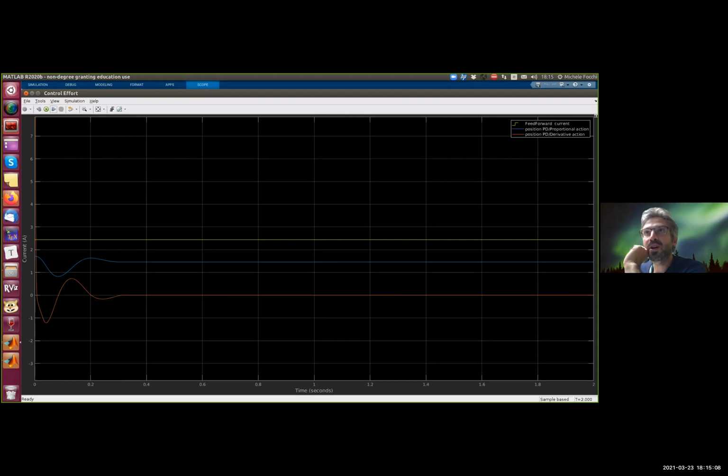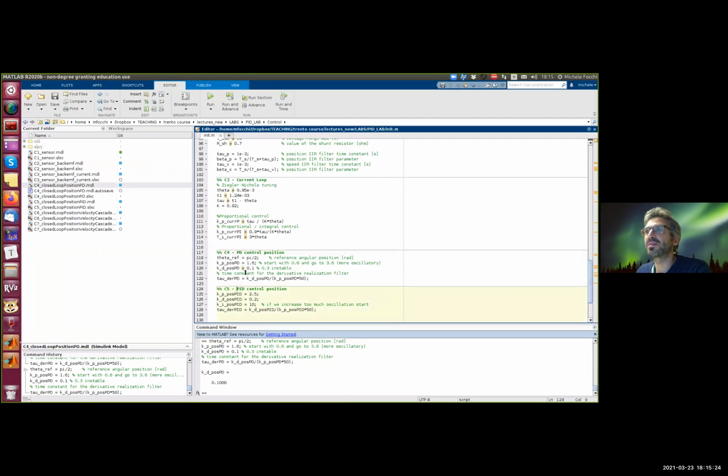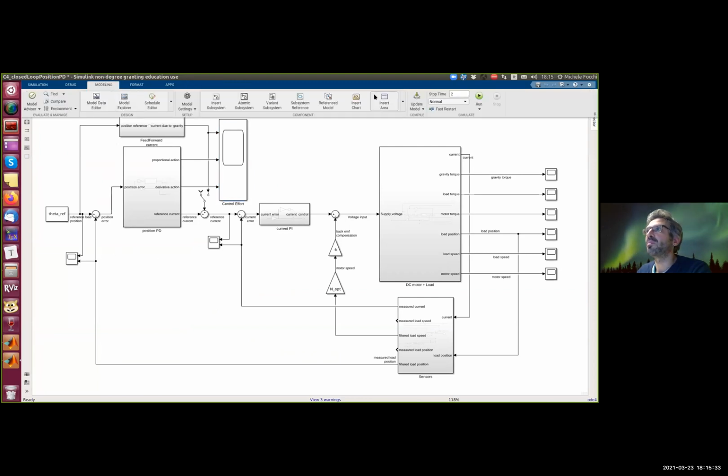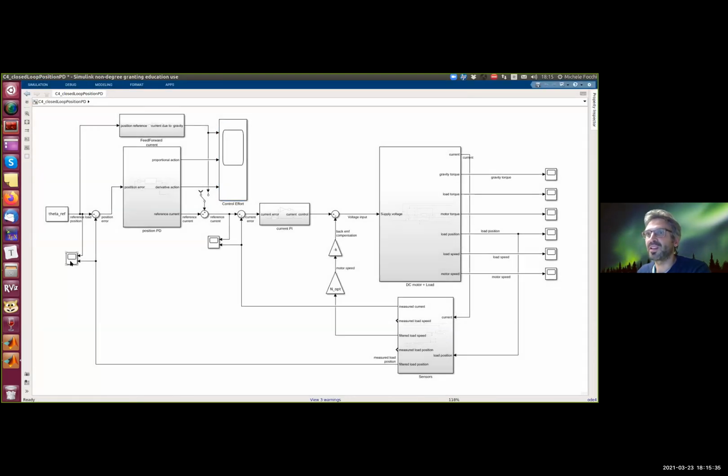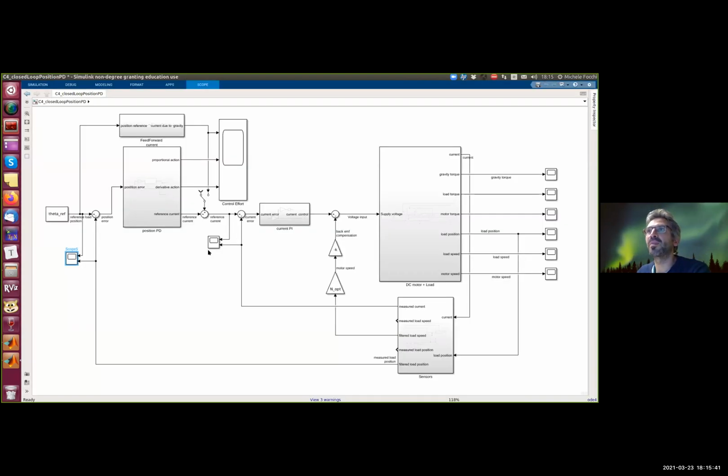So whenever you have a feed forward, the outcome is that you can decrease the feedback controller gains. If you don't have the feed forward action, you would have to increase the feedback gains. So now let's try to increase, but then you remember that if you increase too much, the system can become unstable and the response deteriorates. So again, it's a tricky problem. All this stuff that I explained is helping in making a better controller.